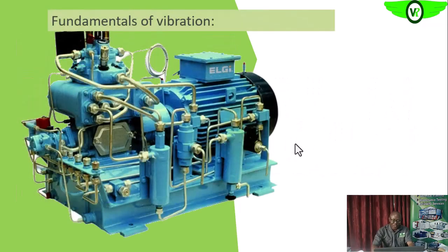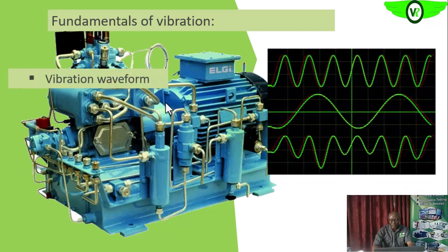So still on the fundamentals of vibration. As you can see on this motor, we can take the vertical here. If there is no space, we look for the closest position where we can take that horizontal information. It's just for you to know precisely what you are doing.